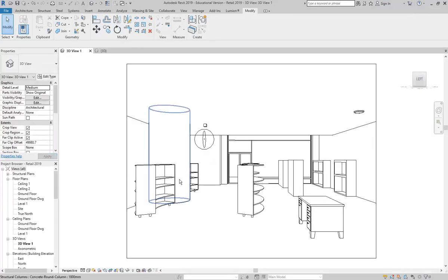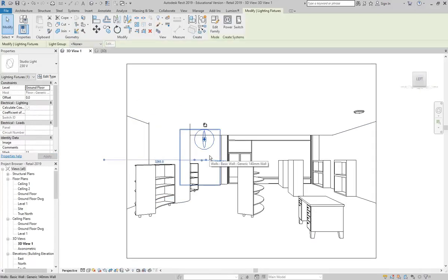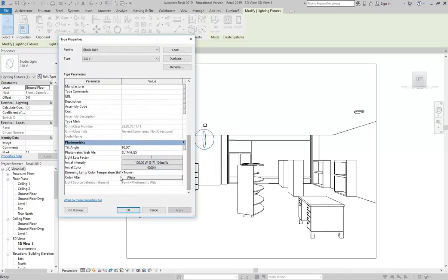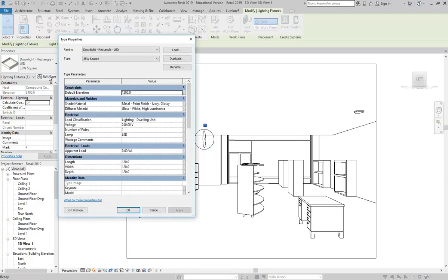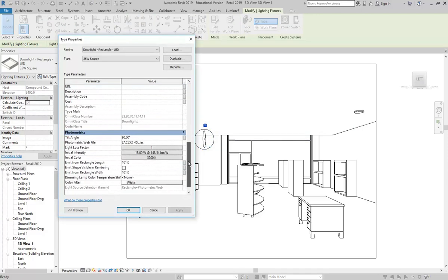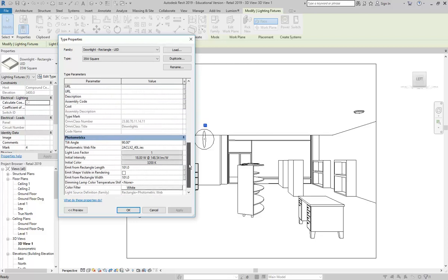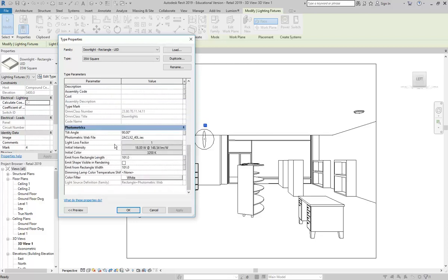So going back then to the other main things that affect your lighting. Mostly I've been looking at distribution, but then you've got the things that you would naturally think about with lights, with brightness being probably the main one. So whenever you select any light family in Revit, and go to edit type, if it's been set up for rendering, and not all of them have been, but if it is working for rendering, then you set the brightness using this initial intensity.